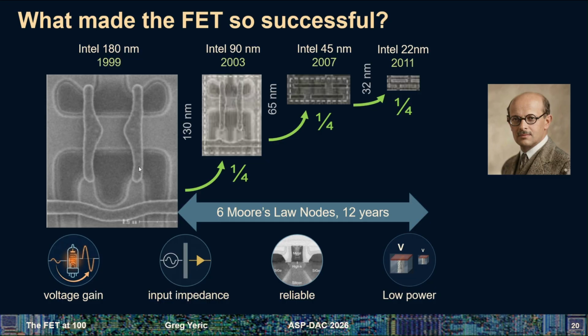So 1, 2, 3, 4, 5, 6, and then you'd have 2 P transistors, P diffusion, 2 N transistors in the bit cell like a prison cell. And then this strip of communication out to the outside world turns on and off the ability to communicate the bit state to the outside world, or the other way around, program the bit. That's called the word line, and that's just because a collection of bits along this line becomes a word in architecture speak. So long story short, look at this, bit cells are shrinking, great.